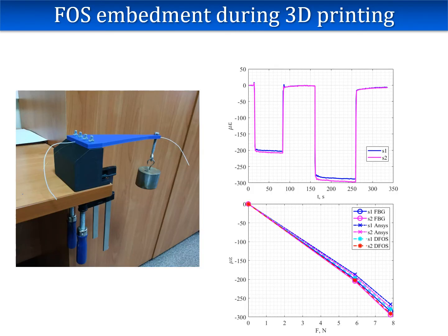On the next slide, the sample in the form of a beam of equal resistance was loaded, and the strains were measured using both types of embedded sensor. The sample was oriented in such a way that the embedded sensor experienced compressive strains. Two levels of load are applied with a delay in time at each step of load.